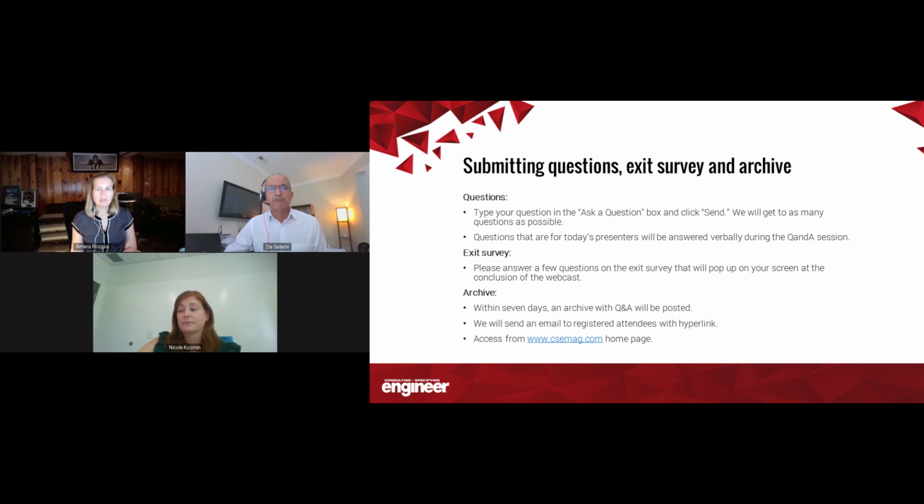Zia, this is referring to one of your studies. Does the data used in the study for harmonics from the UPS come from the UPS manufacturer, or is it part of the ETAP program? Correct. In general, all the electrical software packages such as ETAP, SKM, EasyPower, and more have a library that can be used as a standard when there is no data available.